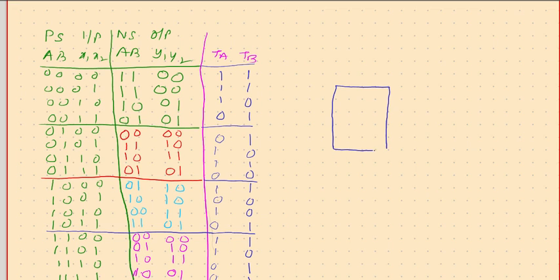So what is the memory? I have a memory with two address lines coming from our current state and two address lines coming from our two inputs. These four inputs give us 16 combinations, and these 16 combinations are put inside.